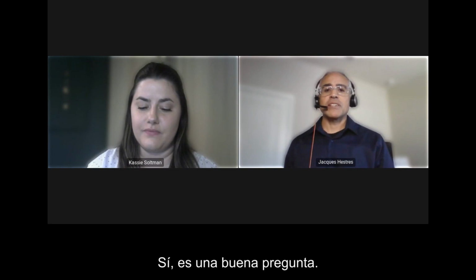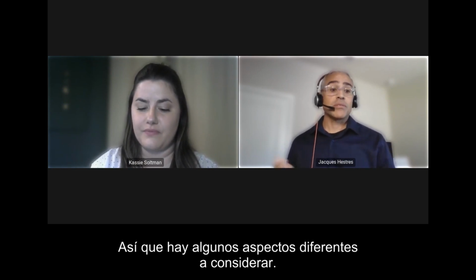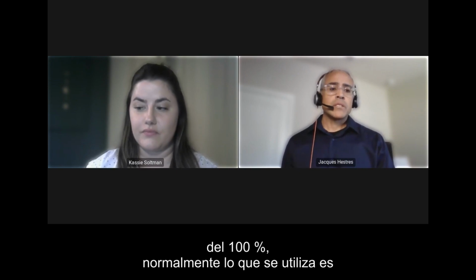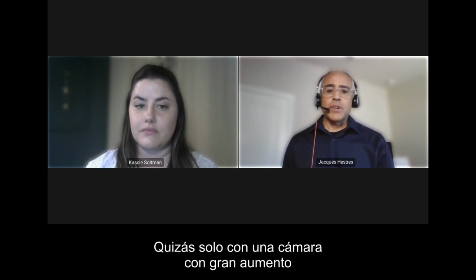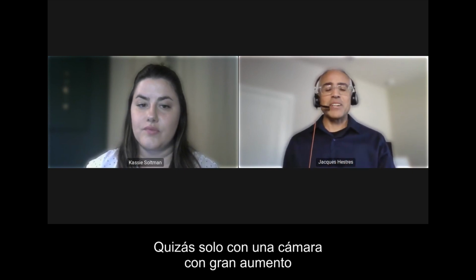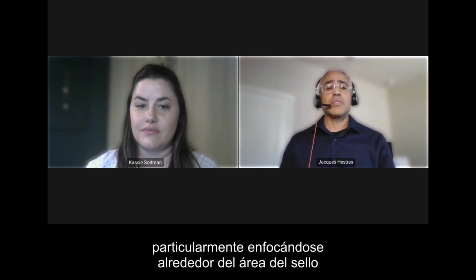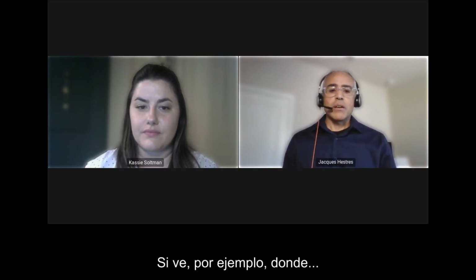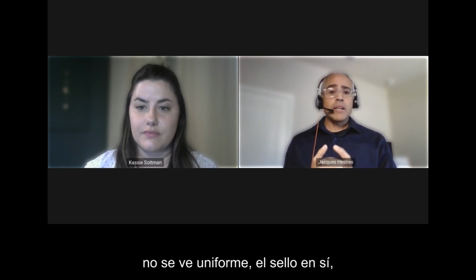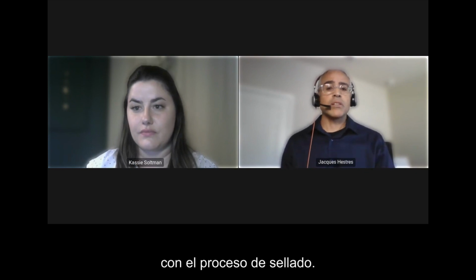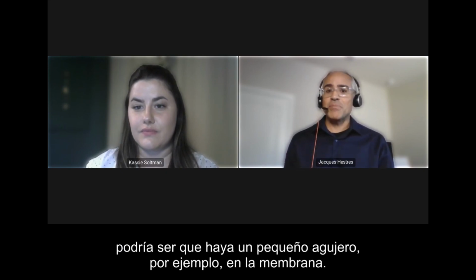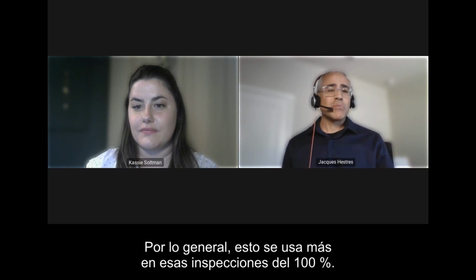Yeah, that's a good question. There are a few different aspects to consider. If you're looking to do a 100% integrity check, typically what's used is a visual inspection, perhaps with a camera at a high magnification. You're looking at the whole area, particularly around the seal area, to verify that there's no breach. If the seal itself does not look uniform, that could give you an indication that there's some issue with the sealing process. You could also see if there's any damage to the membrane, perhaps with light passing through, it could be that there's a little hole on the membrane. That's typically more used on those 100% inspections.